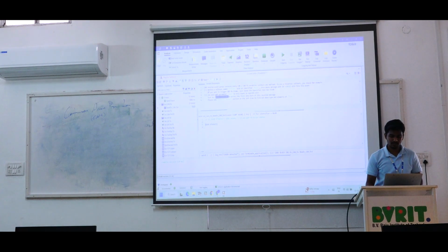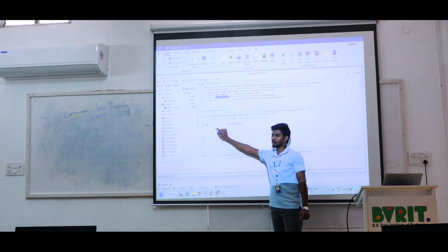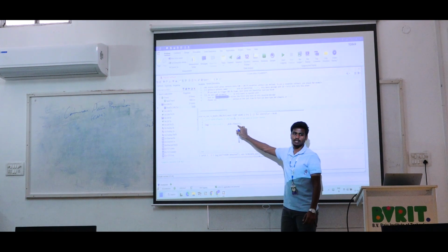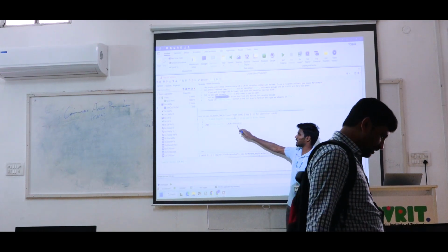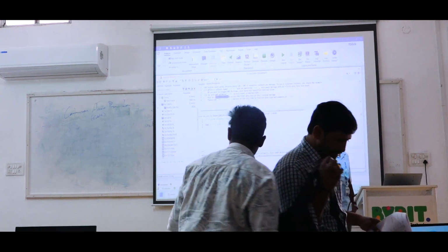Now if we want to see this, you just use the write function, the same concept with double quotes. For example, I have something like vehicle speed. You just type anything in our coding, vehicle speed is, then double quotes, comma. So the can F data means whatever byte value it is sending, we are able to print it here. So from the byte value of F data of 0, it is going to print whenever it receives the message number 20.